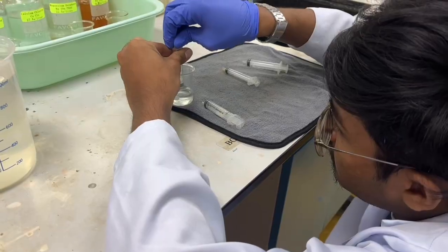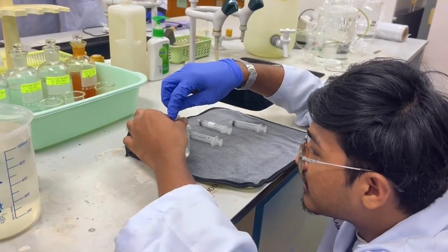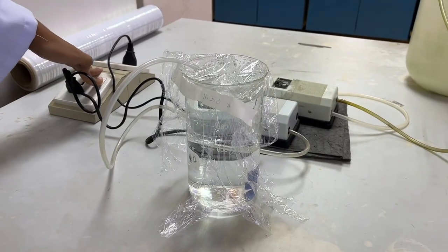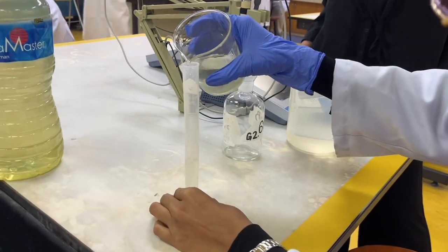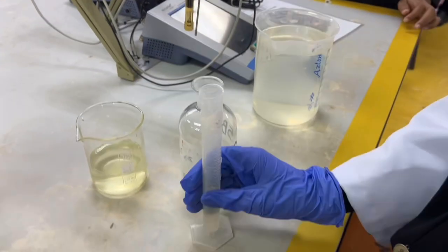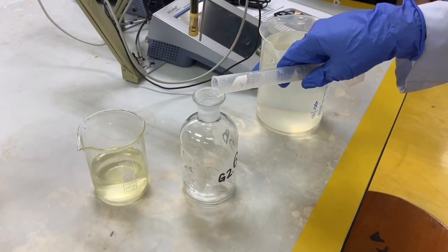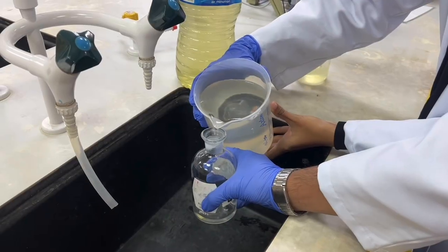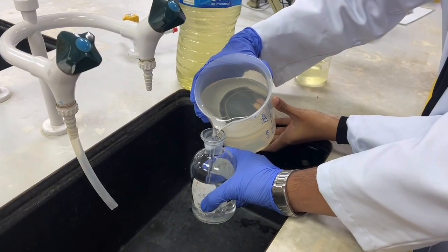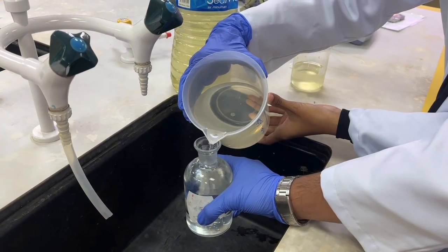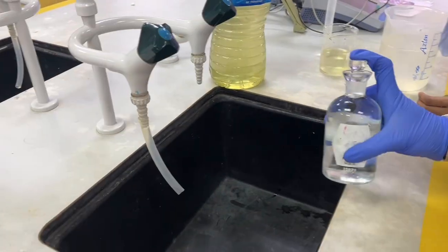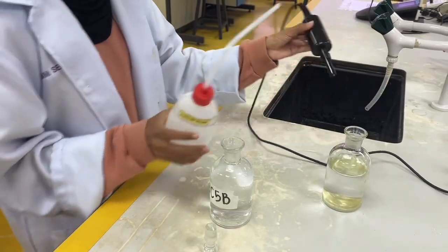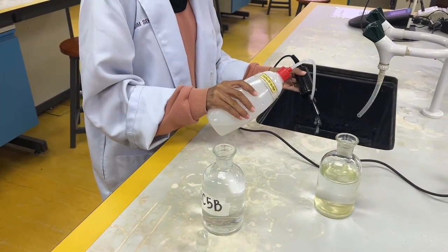with phosphate buffer, magnesium sulfate solution, calcium chloride solution and ferric chloride solution, where the solution will be aerated for at least 2 hours to ensure that it is saturated with dissolved oxygen. Then measure the water sample with a measuring cylinder for 10 ml and pour it into the BOD bottle. Then fill up the BOD bottle with dilution water until the neck of the bottle. Close the BOD bottle with its cap